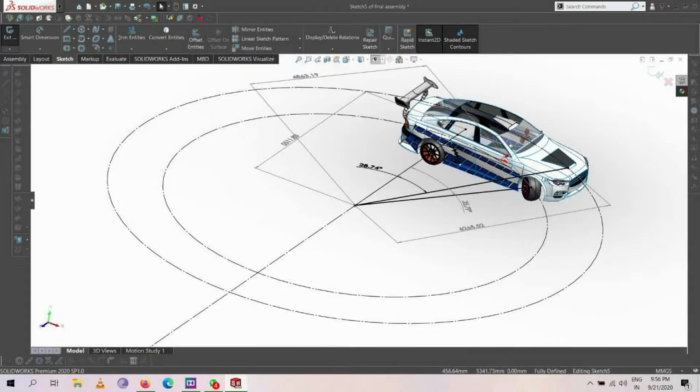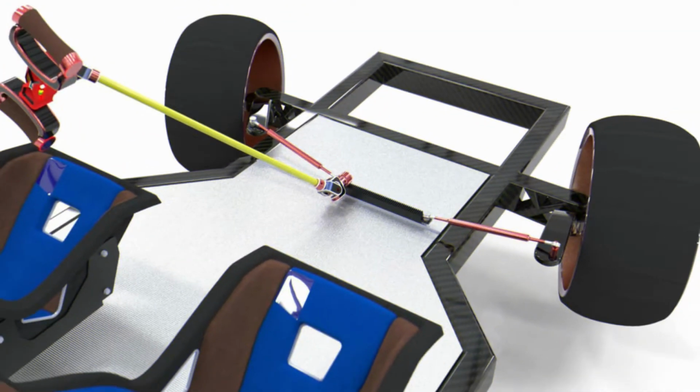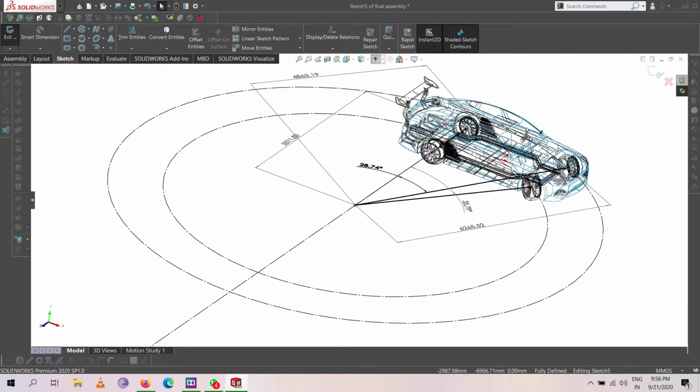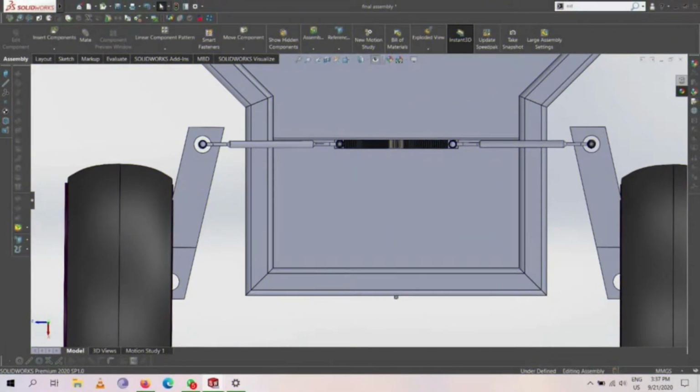If both tires are at the same angle, then they have to slip around some uncommon point, so it wouldn't work as well, especially at high speed. The Ackermann principle is great for solving this problem. Each tire has a path of different radius, which means all tires are rotating at a different rate. The one on the outside travels a further distance than the one on the inside in the same amount of time, so it's rotating more quickly.